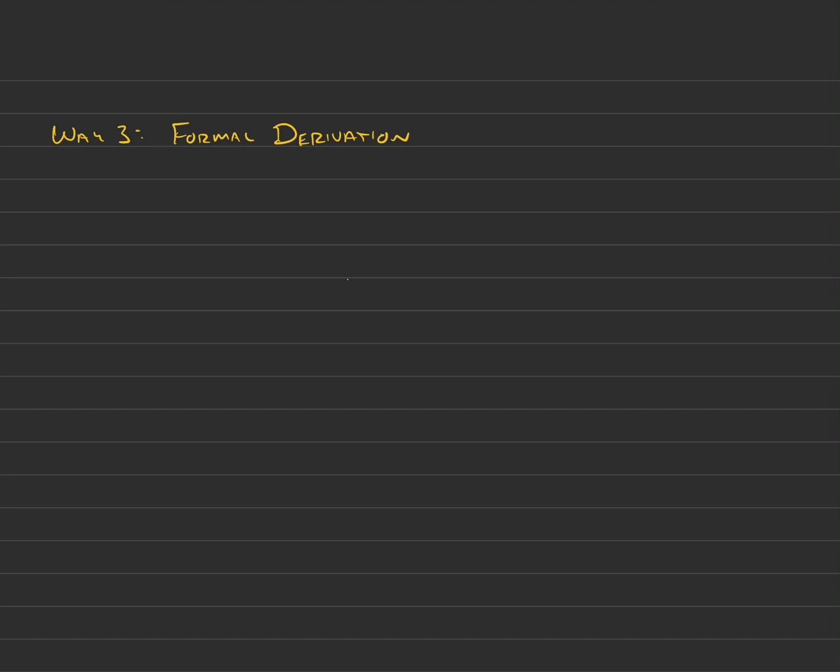Well, again, it's kind of similar to the power derivation, in that what you think about is this fluid, a column of fluid that flows through it over a time dt. Over that time dt, it's going to travel dx, right? But what you're looking at is from the reference point of the inlet only, right? So the dx is representative of maybe the volume that you've actually pushed into the control volume, right? So you've pushed a volume that looks like this into the control volume, and this is your dx here.